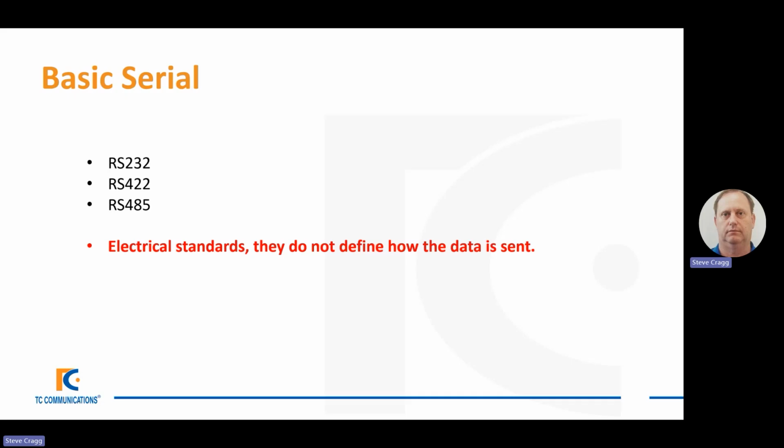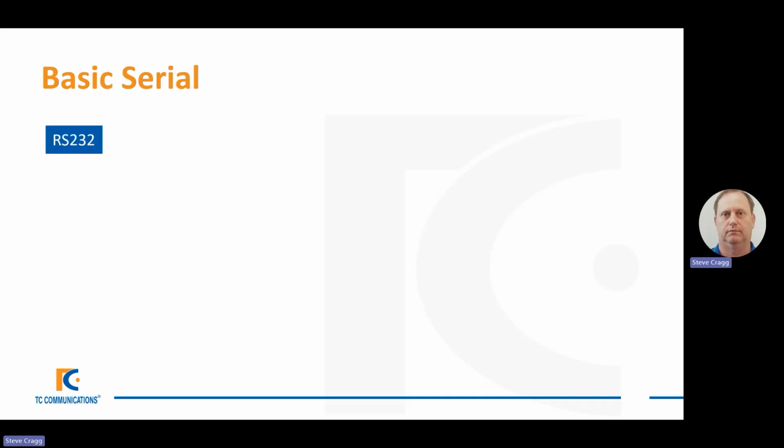In other words, they use the same voltage for a 1 and the same voltage for a 0. However, how the data is actually being sent, in what format, how many bits, and so on, is not defined by these standards. So you are free to use that. Now, there are some fairly common ways that this is done, but they're not part of these standards. These standards are electrical. So let's look at the first one, probably the granddaddy of all.